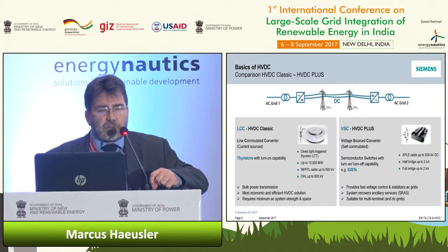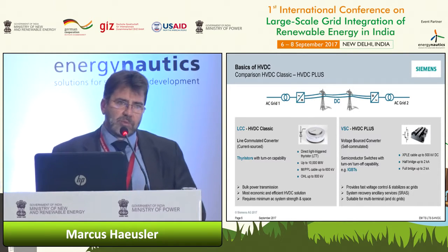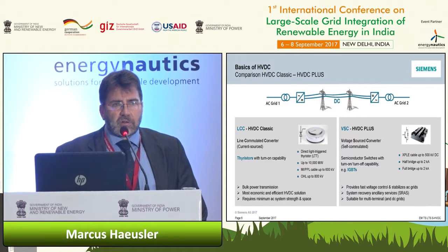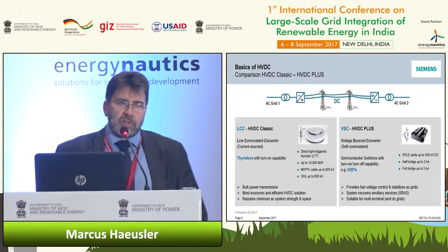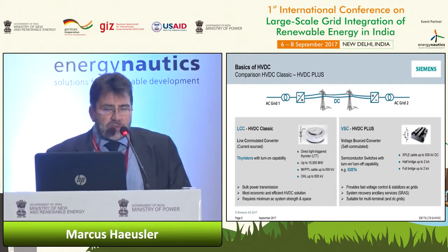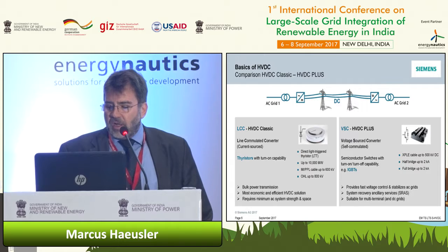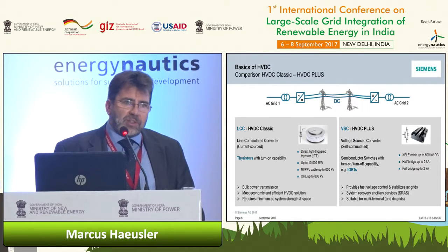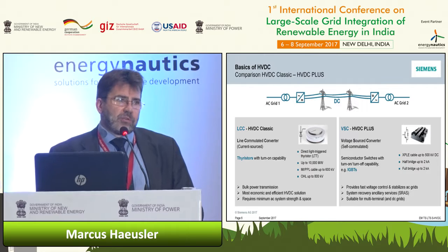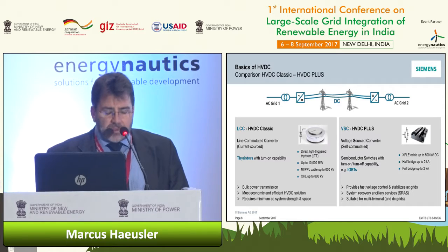In Germany, in Europe, offshore wind farms are one excellent example where this technology is used very successfully. The wind farms are setting up their own islanded system, and the DC link can operate very stably with these wind farms. Also, an additional advantage of this technology is that XLPE cables can be used because the voltage is not reversed. And we can also easily construct not only a point-to-point connection with 2 terminals, but also multi-terminal, or even, as an outlook for the future, DC grids.